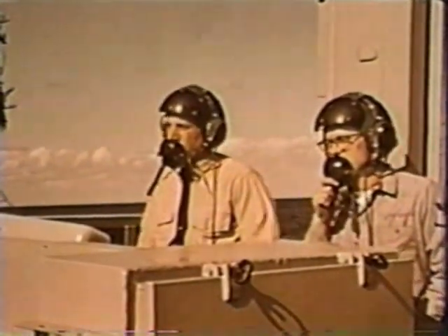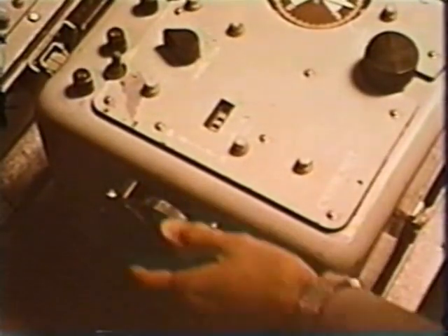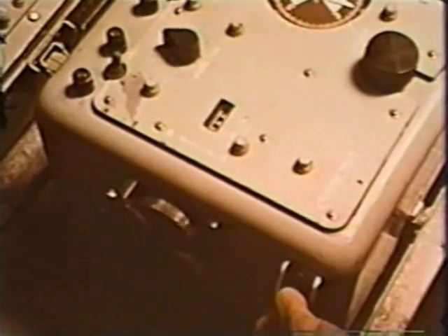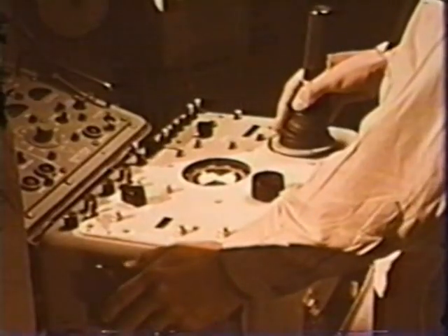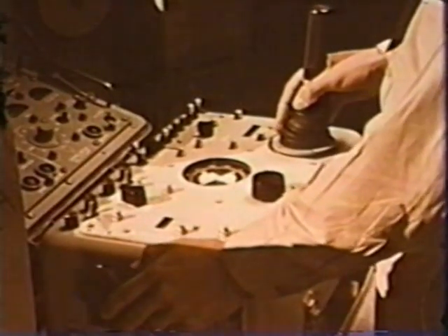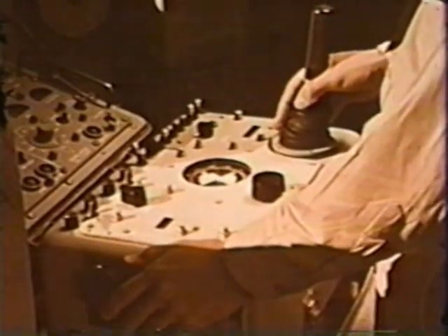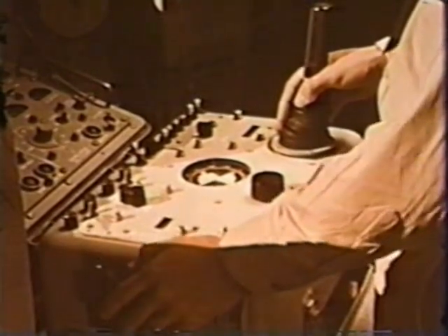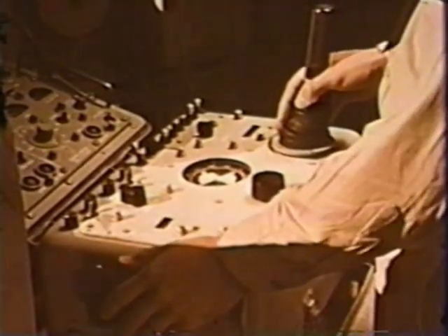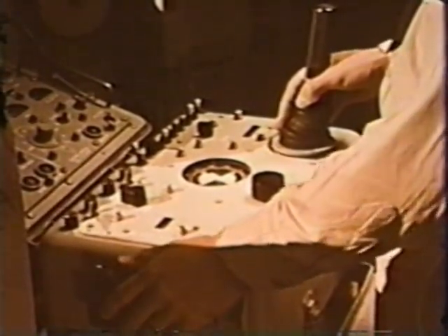The altitude rate switch may be used when at altitudes above 150 feet. The altitude knob is used with the maneuver stick to recover the drone. During its approach to the deck, the drone may rise slightly as it enters the ground effect. It requires careful balance between the two controls to bring the drone through turbulence to a smooth landing. Ship motion may add a complication.